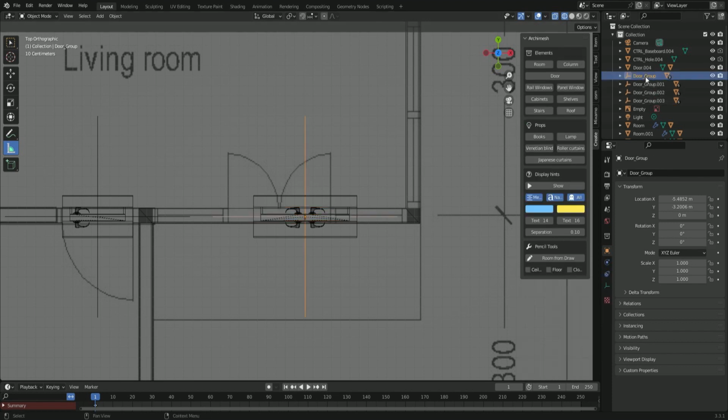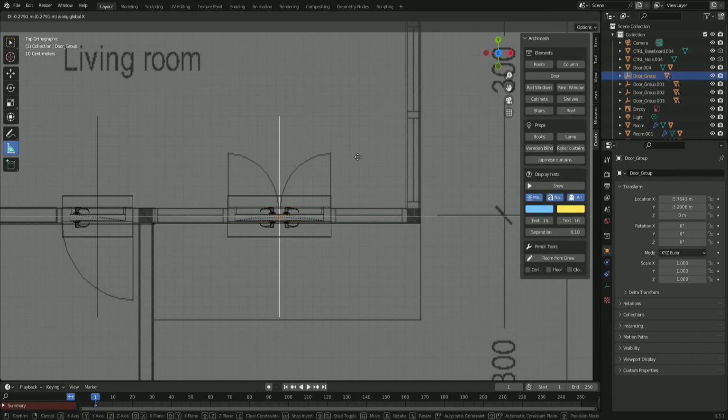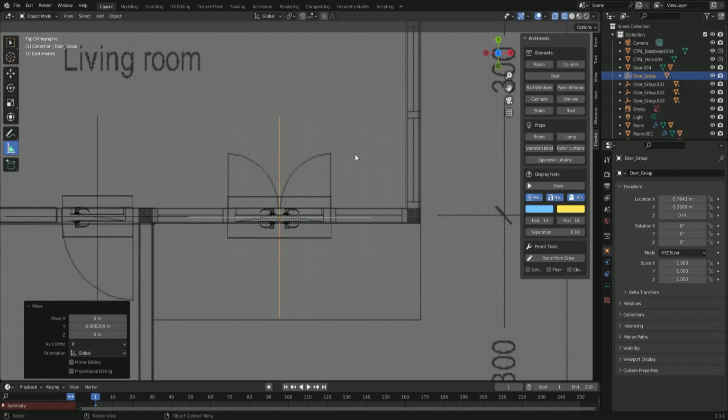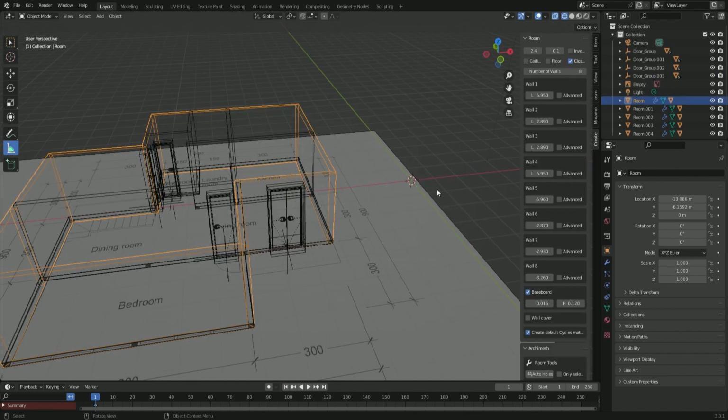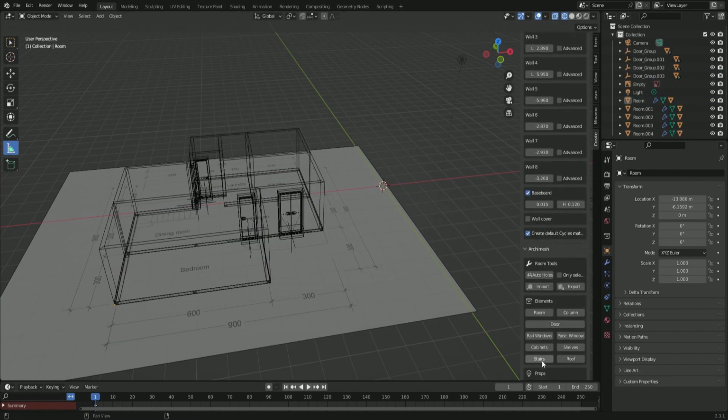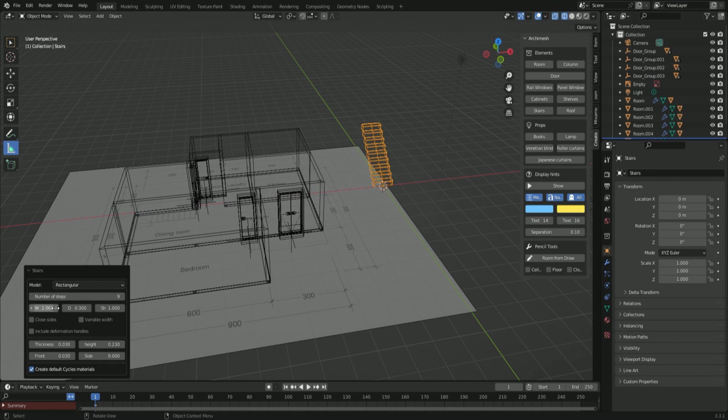Here's the staircase. Now just going to tap stairs. All these different options at the bottom left, you can change the number of staircases, the width, the style. What I would suggest is you do everything you need, the number of stairs and the height, when you generate it, because once you move the stairs, unfortunately you can't change the number of stairs and the height and everything.